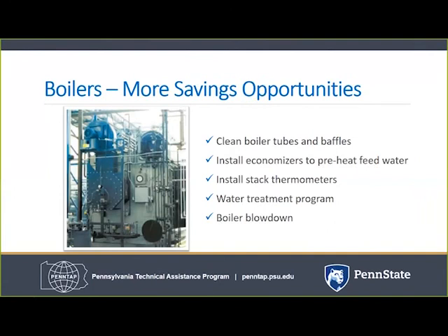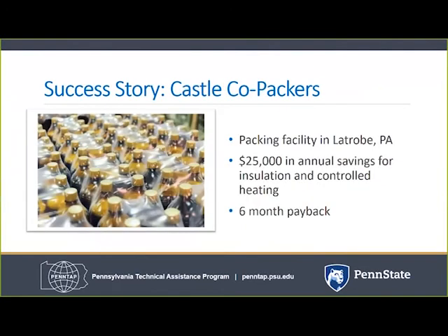Here are some more saving opportunities. Consider installing economizers to preheat boiler feed water. Clean boiler tubes and check for broken baffles. Install thermometers in the stack to monitor flue gas temperature. Rising flue gas temperature indicates when boiler cleaning is required. Implement a water treatment program to prevent scale and corrosion in the boiler. Have a service technician perform periodic boiler blowdowns to purge solids and particles. These steps can result in significant savings and a quick payback period on your investment.